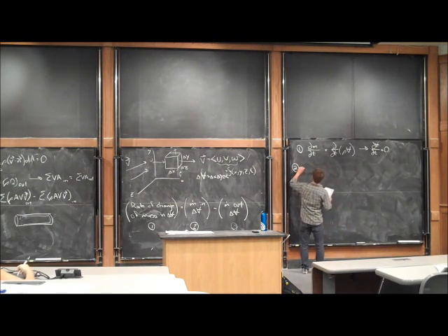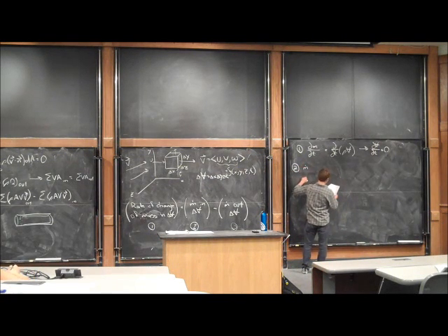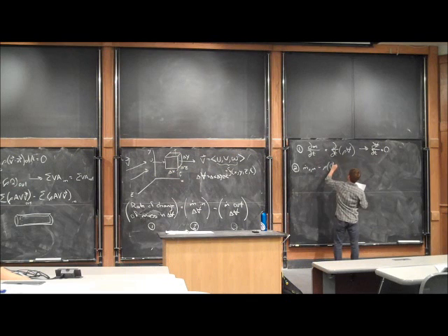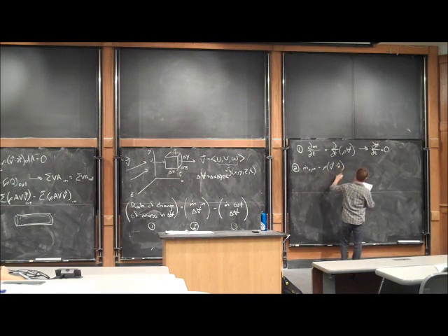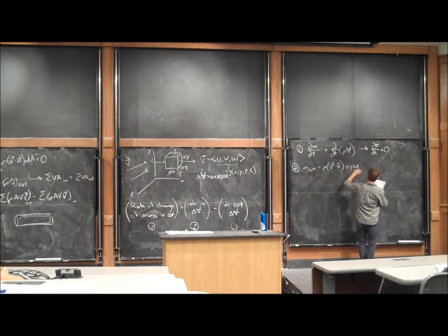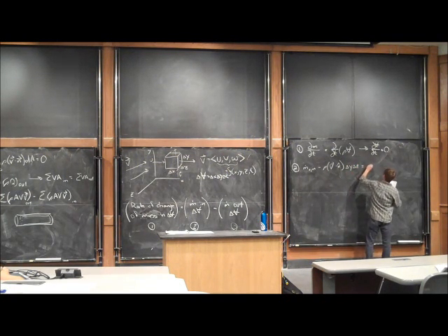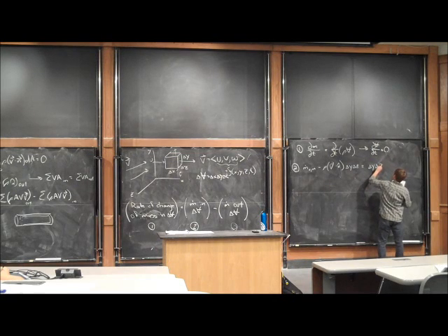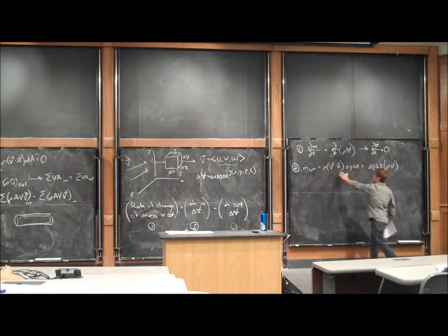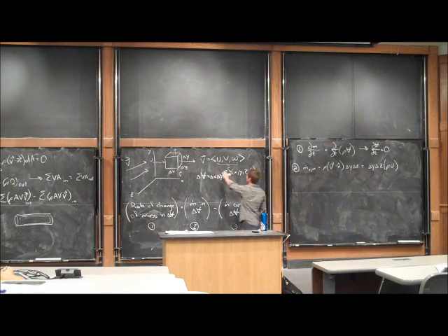So the rate of change of mass in the x direction into the control volume is going to be equal to rho times V dot x hat times delta y delta z, which is delta y delta z times rho u, where u is V dot x hat, or the x component of the velocity.